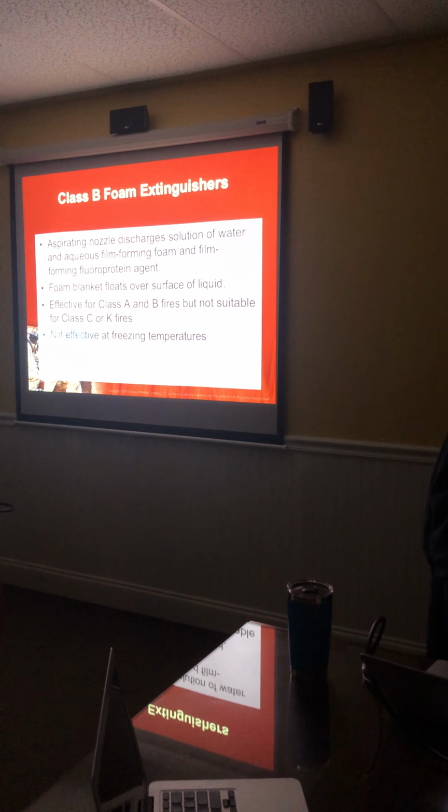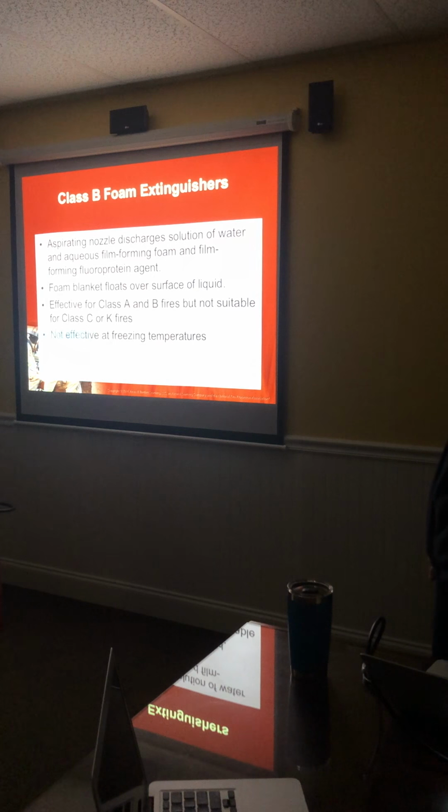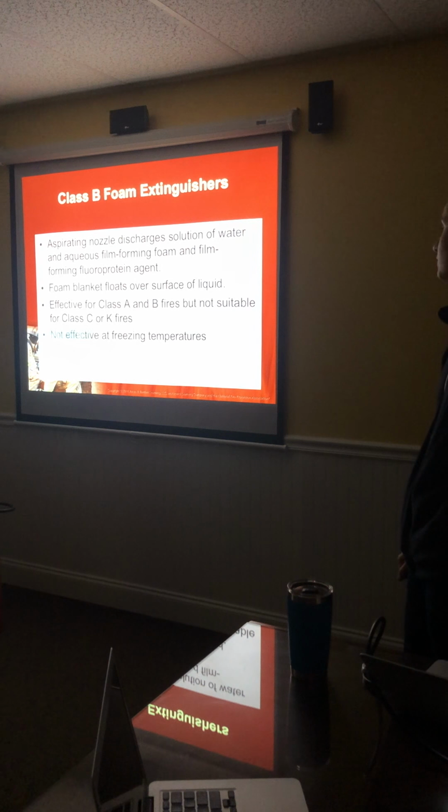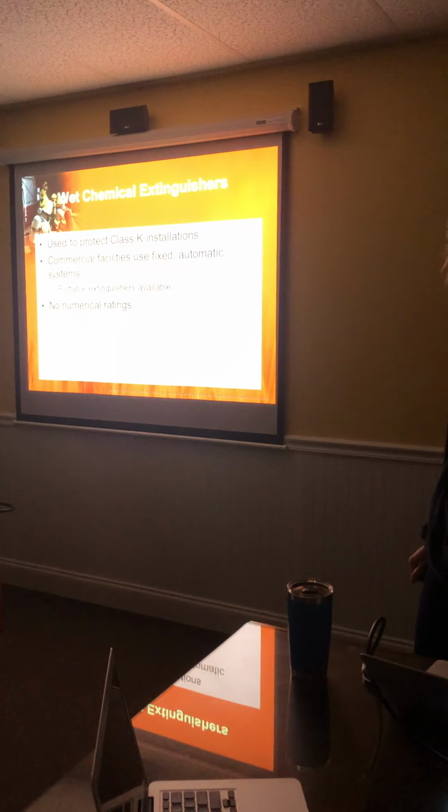Class B foam, aspirating nozzle discharges a solution of water, and it forms a foam blanket that covers the surface of the liquid. It's effective for Class A and B, and not suitable for C or K fires. And it's not effective at freezing temperatures.